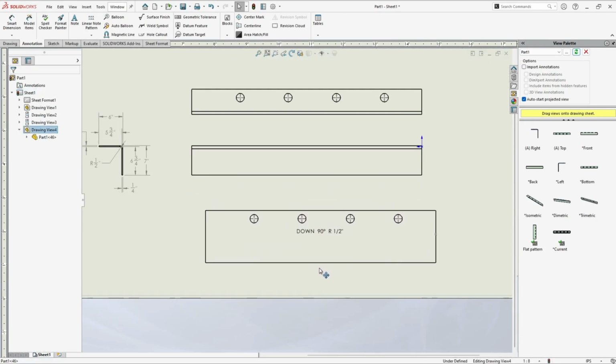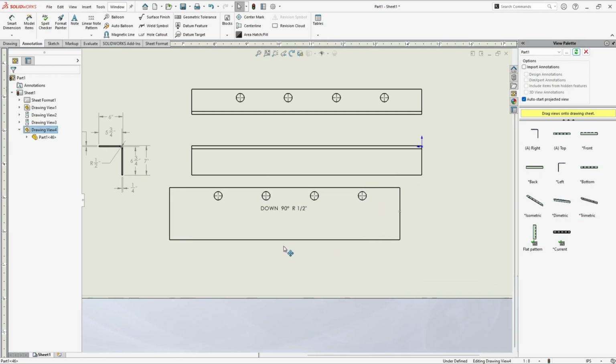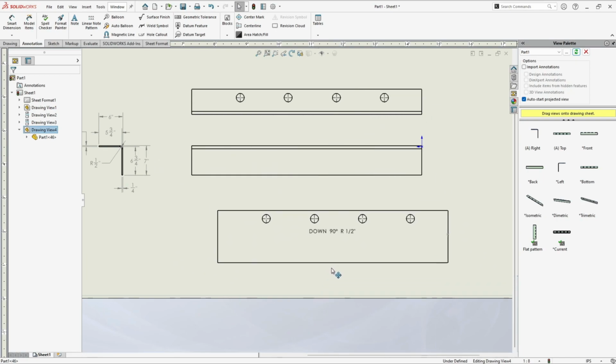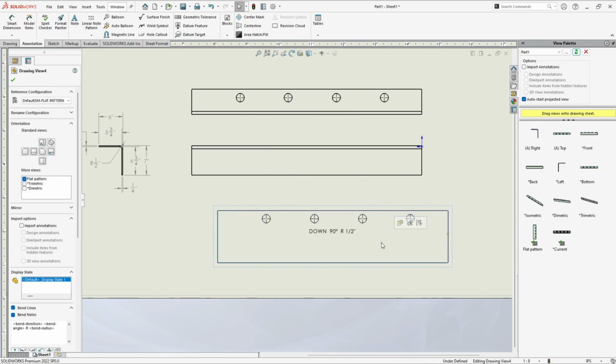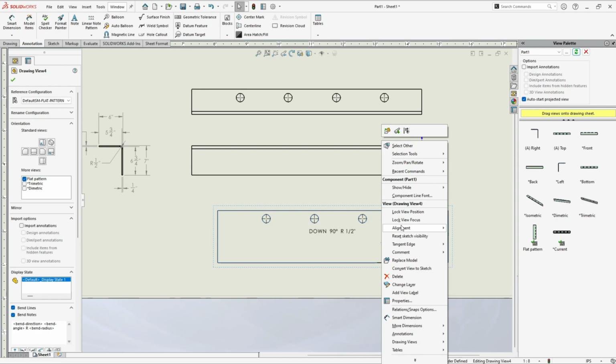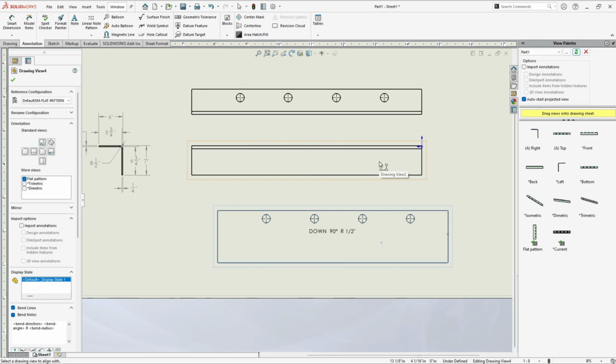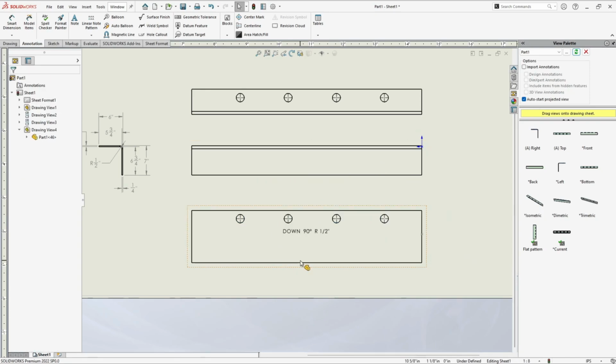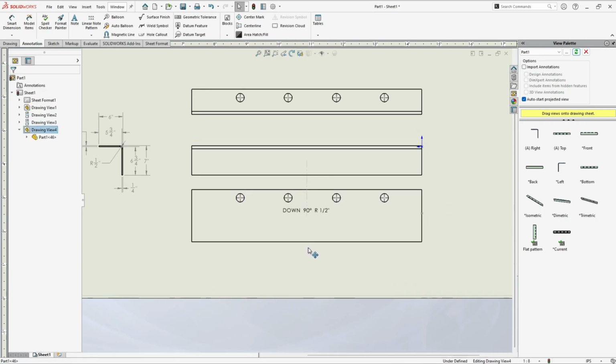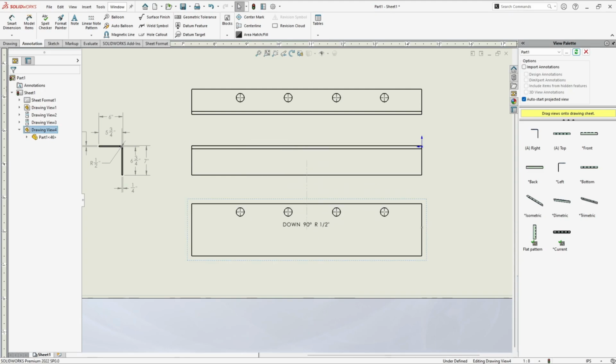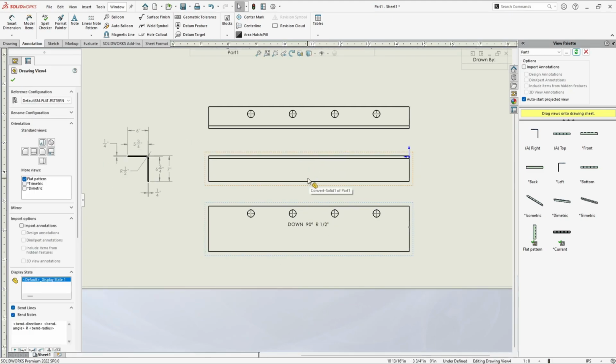You can drag and drop it anywhere, but you can see it is not oriented to any of the views. For that, you can select this flat button view, right click, and here we have the alignment. So in this particular case, we will be going to use align vertical by center. Click over here and let's select this particular view. So our flat button is aligned to the center of this view which we have, that is the front view.